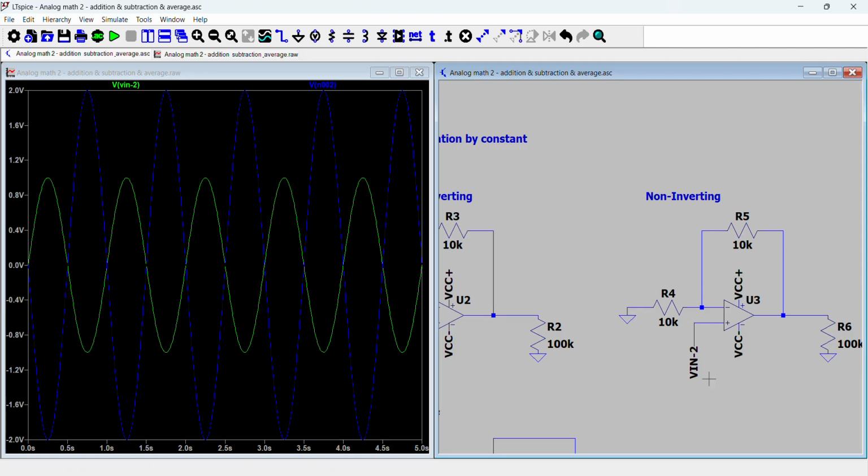However, because of the way that this is set up, the gain can no longer drop below 1, because now the current across here is no longer 0 minus the output. It's 0 minus the actual input. So this introduces a 1 in the gain equation. And you can derive that by basically taking Kirchhoff's current law around this point.